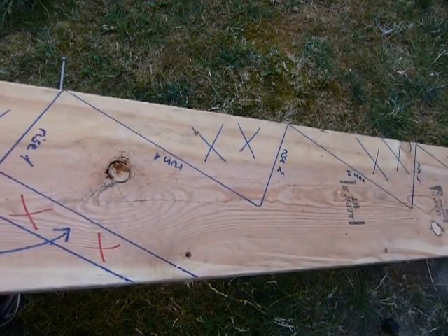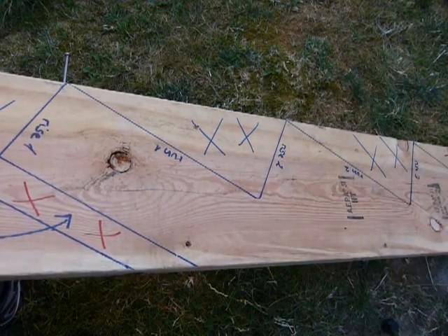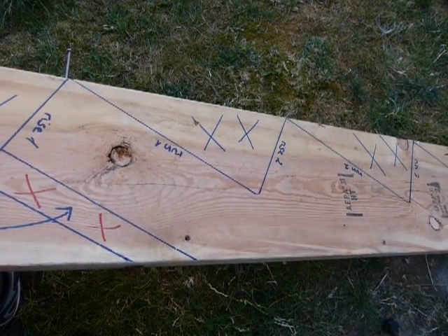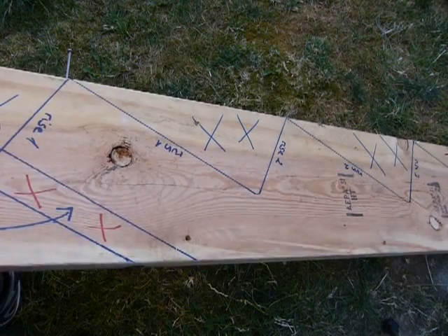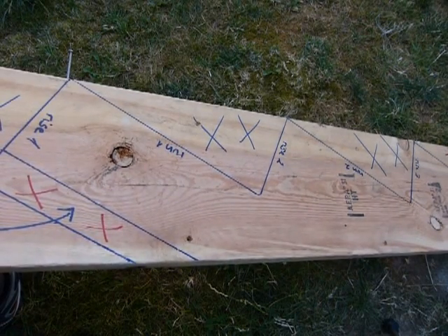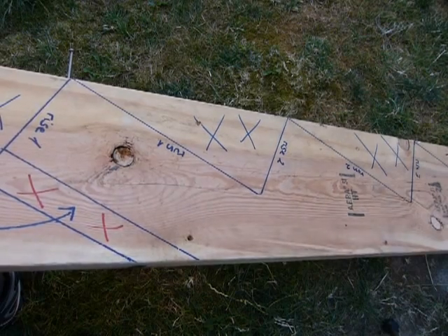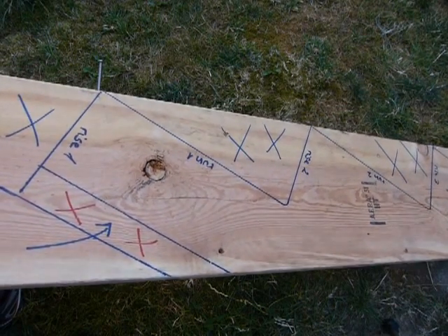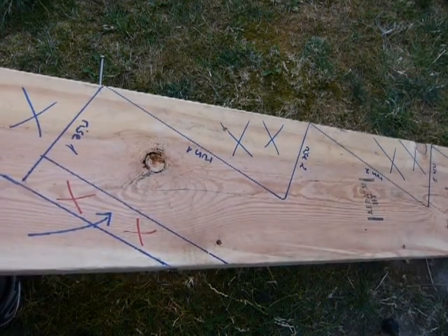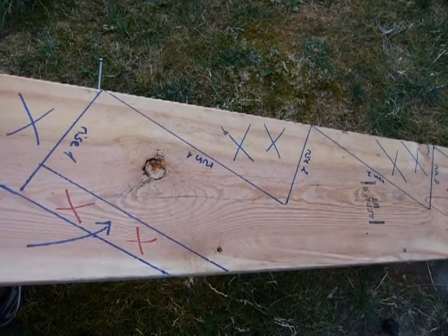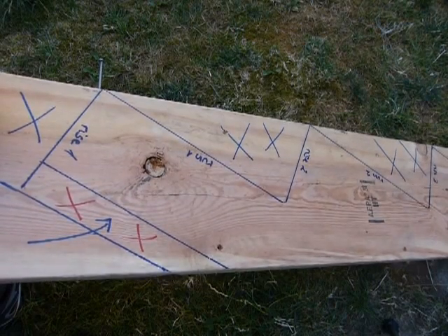Remember the part of the building code where it says stairs shall have uniform rises and runs. So do these shortenings carefully, and this is why calculation is very important. Good stairs don't just happen by accident or by mistake. They need to be carefully laid out and carefully calculated. Now we're good to go to make the cuts.